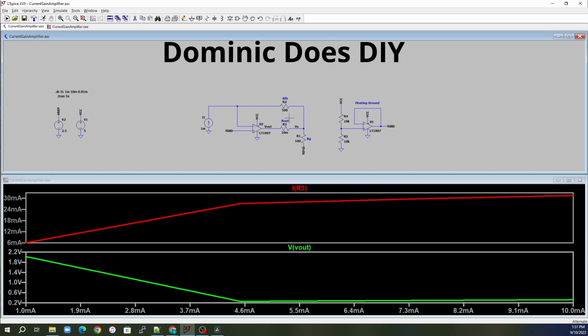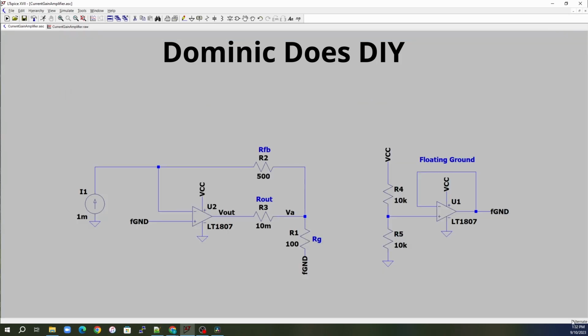The only other thing that we'd have to calculate is the current, and whether these op amps are able to handle it. This is very small, like even with a 4.5, you're looking at maybe 30 milliamps as an output, right? We can see up here, when it saturates, the op amp is going to be sinking 26 milliamps. That's usually nothing for an op amp. That should have no problem being able to sink that. And now we've got our gain against that R3 resistor just the way we want it. So there we have it.